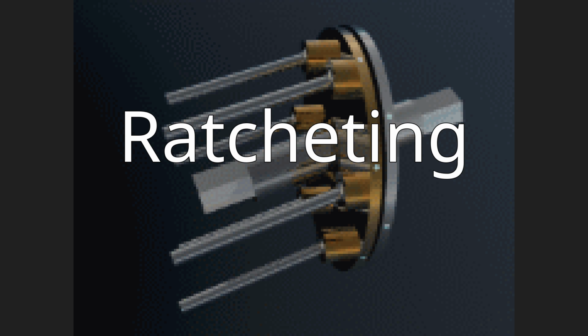The drawback to ratcheting CVTs is the vibration caused by the successive transition in speed required to accelerate the element, which must supplant the previously operating and decelerating one. The design principle dates back to before the 1930s, with the original design intended to convert rotary motion to oscillating motion and back to rotary motion using roller clutches.